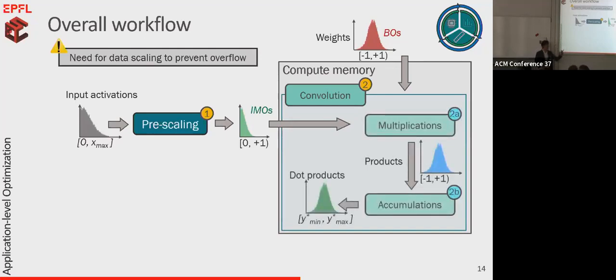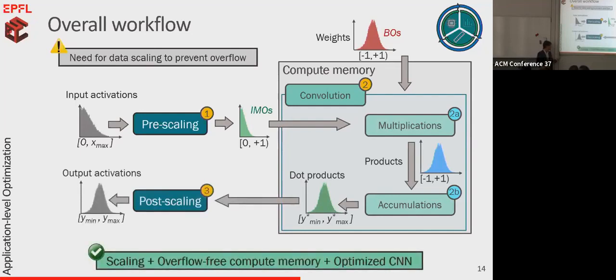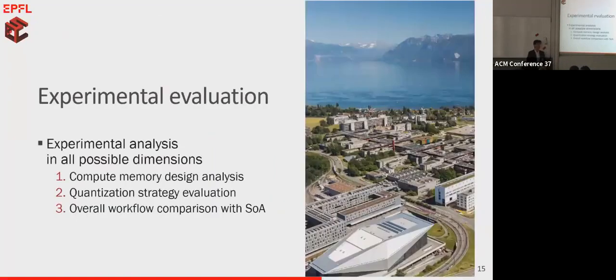These dot products are actually computed using pre-scaled input activations, so we need to scale them back to retrieve the expected output. As you see, we are combining the scaling technique with the overflow-free compute memory design and optimized quantization in this case. So let me now show you the results. Here I'm going to show you different experiments to evaluate the different aspects of this methodology. I will focus on the hardware design, the evaluation of the quantization strategy, as well as the overall comparison with the state of the art.